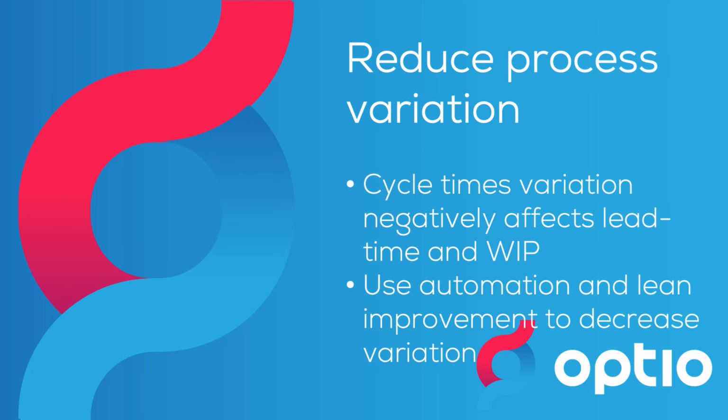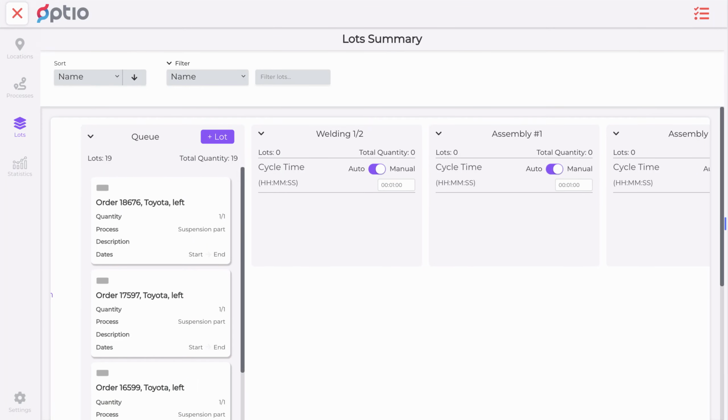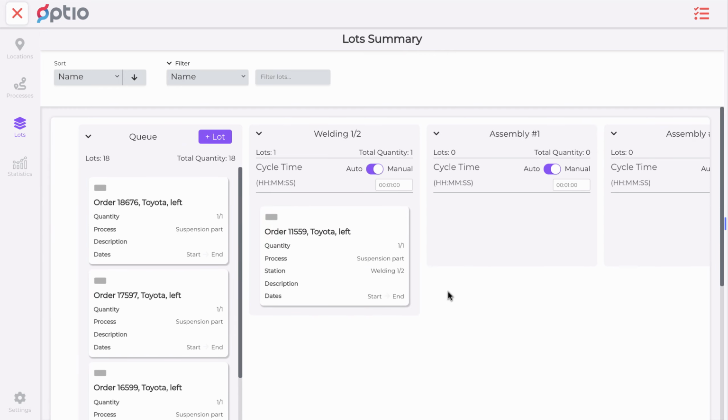We have seen what single item flow in a well-balanced line looks like in a perfect world in which every step takes exactly the average cycle time. In practice, that is not the case, but there is considerable variation, in particular during manual processes like welding or assembly. We are simulating this using a normal distribution around the expected cycle time, which is 1 minute each. So it could be a little more, it could be a little less than a minute.